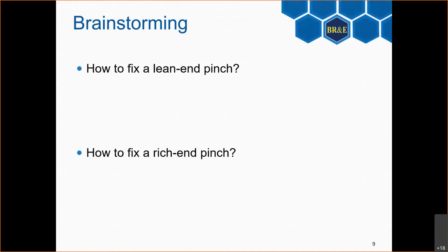What do you think would be a good fix for this case? June is suggesting reboiler duty, and that's correct. As I said, the key word here is purity, and if we don't have pure enough amine, that means that we need to push our reboiler a little harder, regenerate a little better to make sure that we push the lean approach to lower values.